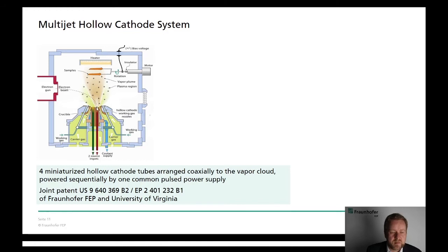An electron beam heats the crucibles and the material to evaporate them, and we have a so-called carrier gas, which is blown with a supersonic jet. So this supersonic jet transports the vapor upwards towards the substrate, which reduces sideward losses of the vapor. And we can even reach non-line-of-sight coating through this jet behavior.